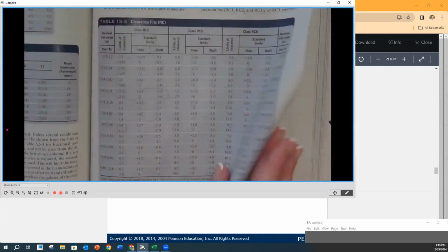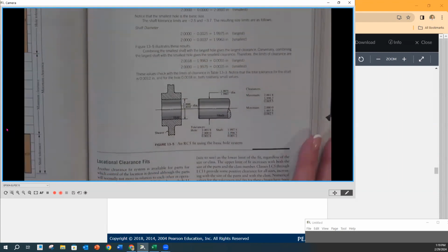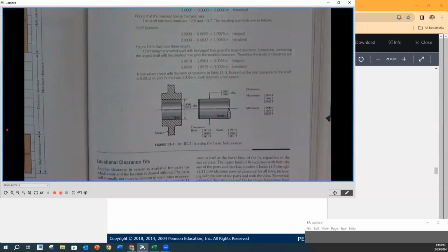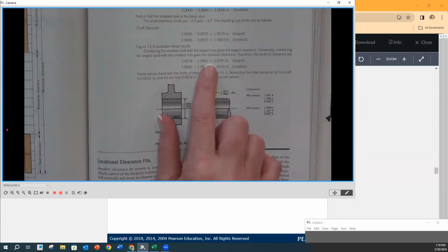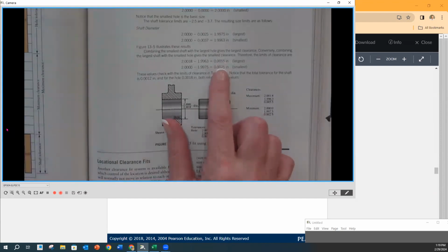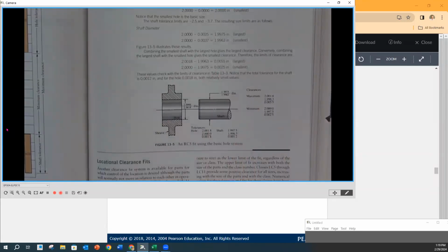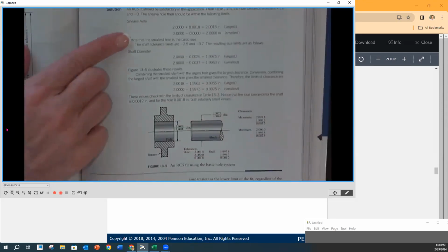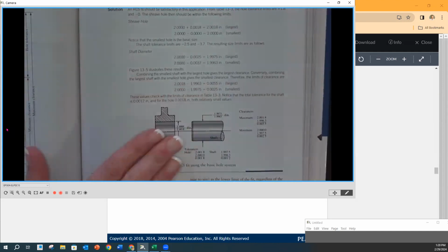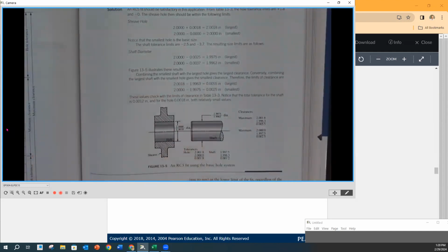All right, so in this example, here were the limits of clearance, which we saw you can get by subtracting those values, or our chart has them there as well. And these are the exact numbers that we had in our chart. And lastly, you'll notice the little sketch down here, showing physically what each one of these numbers meant. The limits on the sheave, the limits on the shaft, and then the limits of clearance aren't part of your drawing, but this is where we would actually dimension them in limit form, so it's easier for the person who's manufacturing and ultimately checking it too.